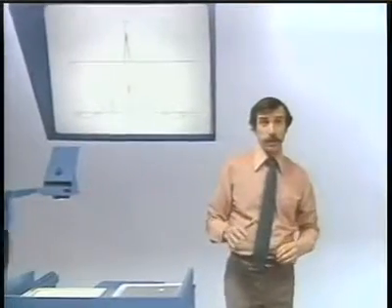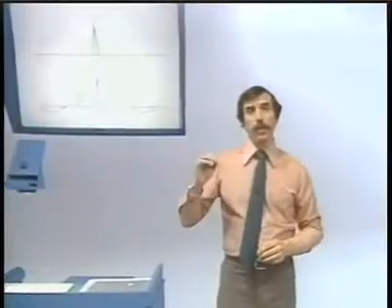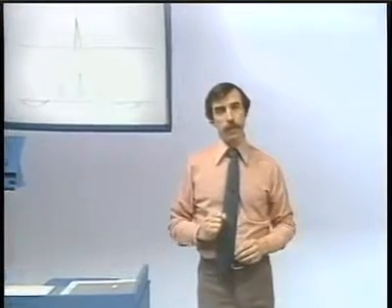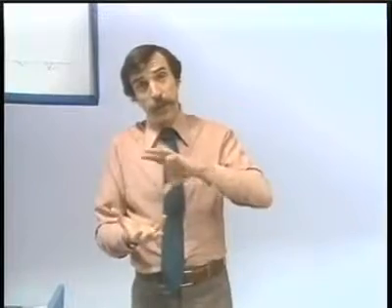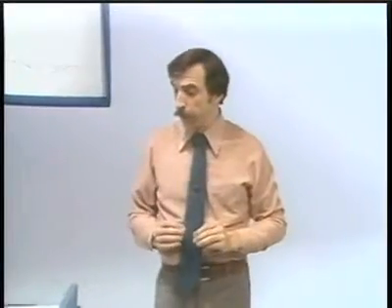Now, it really is amazing that all this depends on is the original signal being band limited and the frequency of the pulse train being high enough so that when you replicate the spectrum in the frequency domain, there's no overlap between these individual replications. And we'll address that a little more in a few minutes. But let me first of all point out that this has a whole variety of very important implications.